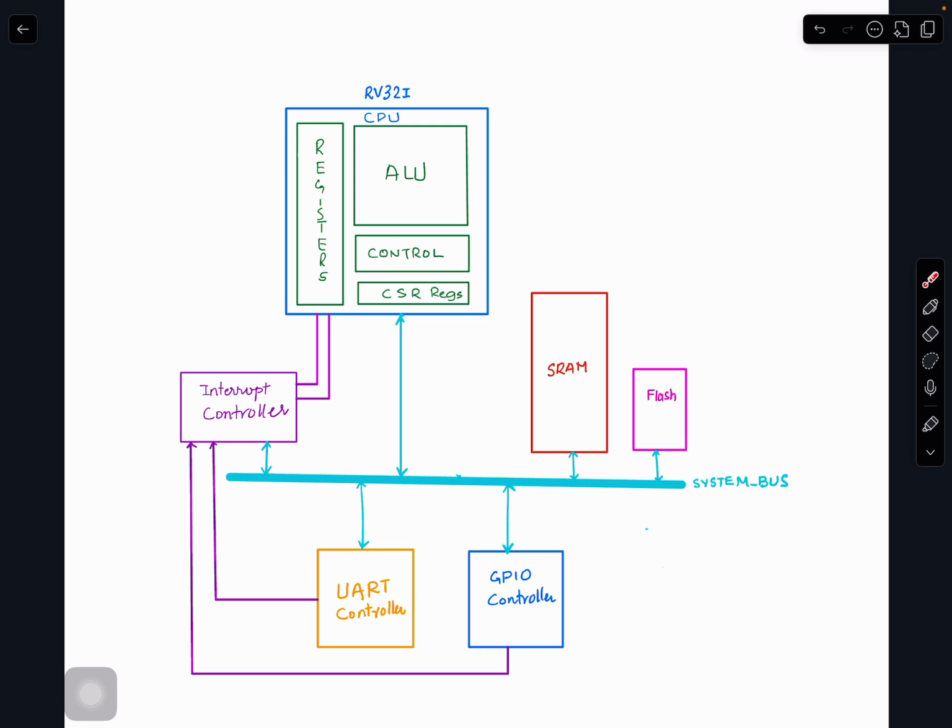And this one I call an ALU, which is where addition, arithmetic operations, and logical operations are done. And then we also need some muxes here and there to control it, right? To process, where we want to direct the output, to register, to memory, and all of that. So these two blocks correspond to that. CSR regs, control status registers, is something we're going to study. And these are registers. We have done that.